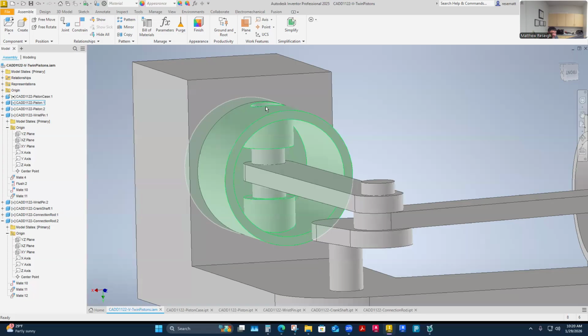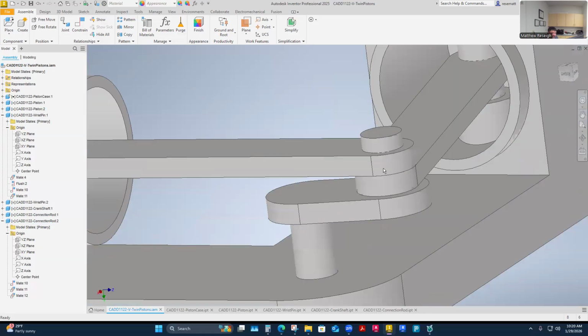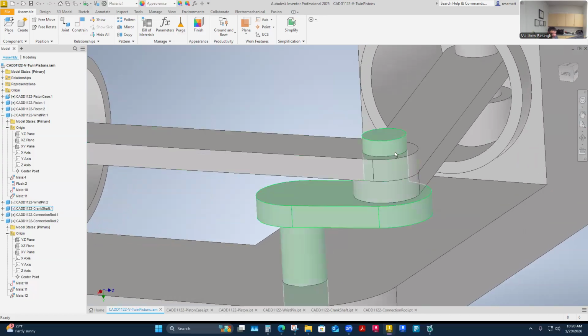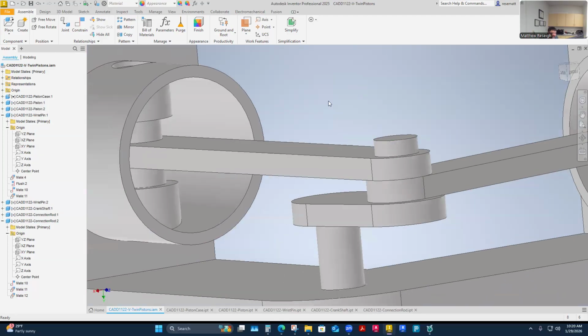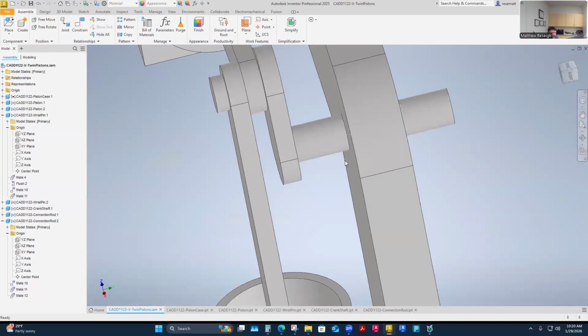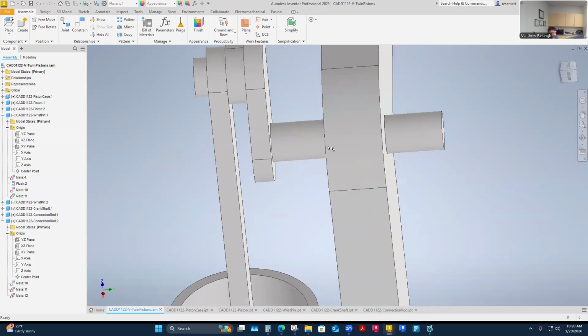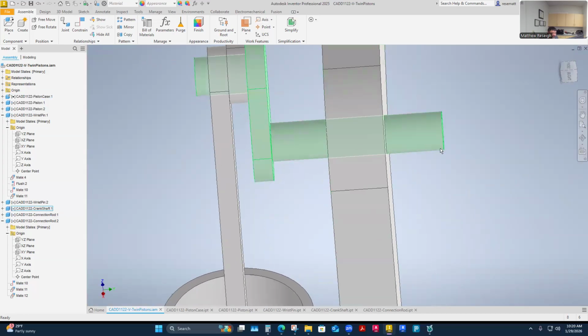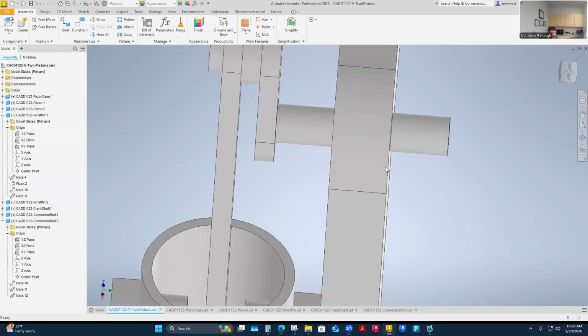So to me, I need like 4 pieces of hardware to hold all this in alignment. Then I come over to here, and I don't want this thing to pop off this shaft. So I can put another snap ring on the top here to keep these from lifting off. That'll be good. I might need to put one here and here to hold this crank from falling through, because this thing would just slip back and forth through here.